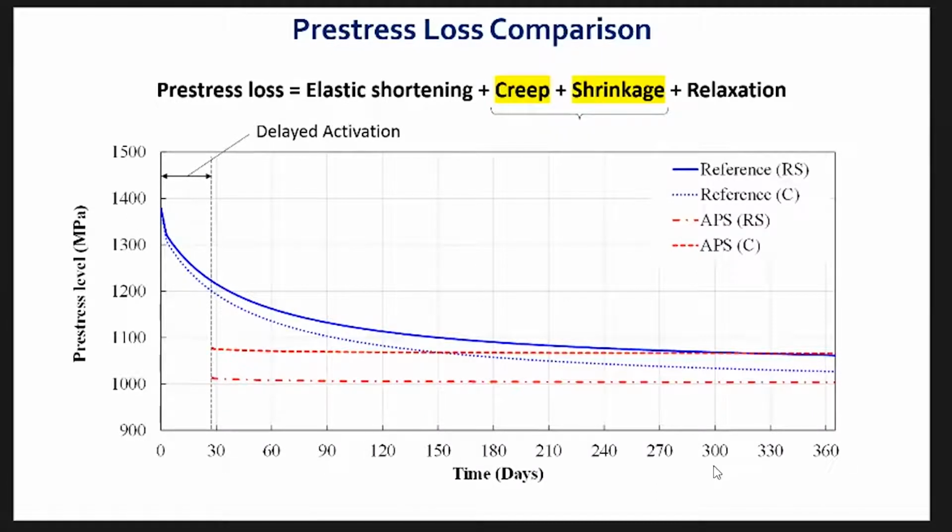So you see here the blue curve, that's conventional steel pre-stressing after releasing the wires a couple days from casting. And then the red is the APS. Now the APS, the beauty about it, because we're not using hydraulic jacking or stressing, you can use any mold, not necessarily the one used for pre-stressing, whether it's the carousel or the cast bed.